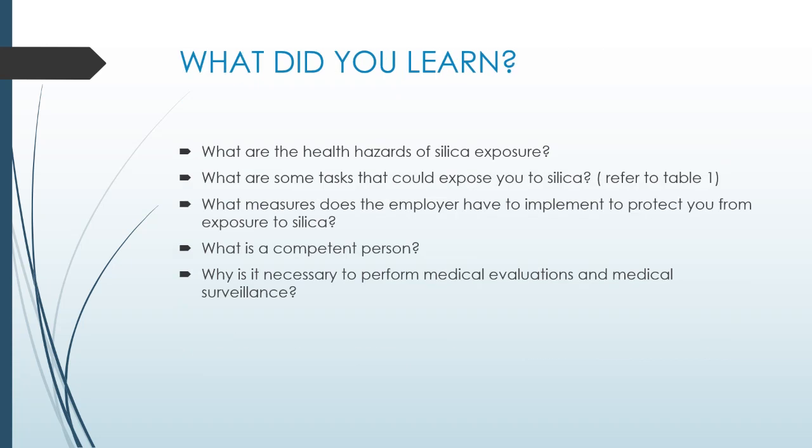So what did we learn? We talked about the health hazards of silica exposure, and unfortunately there wasn't any good news. Silica exposure causes lots of lung diseases: silicosis, pneumoconiosis, lung cancer, COPD. What are some of the tasks that could expose you to silica? Grinding and cutting and demolition of drywall and mortar and bricks and sidewalk and concrete. The tasks are laid out in Table 1, what could expose us and the kinds of tasks that we perform. And looking over it, it's pretty inclusive.